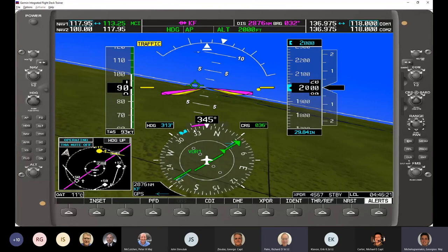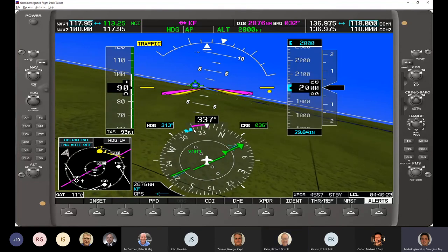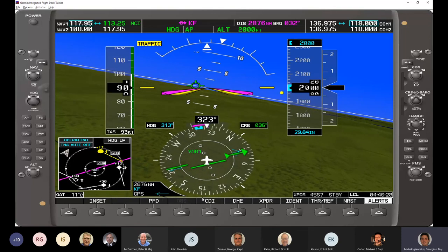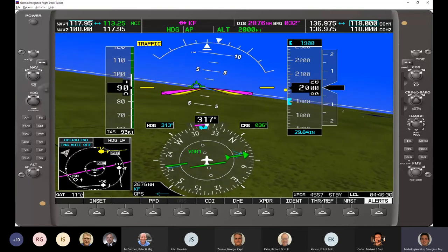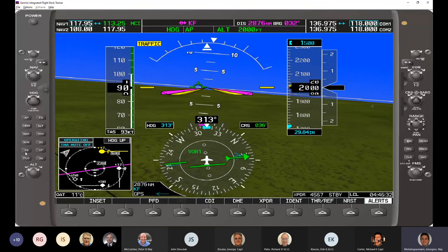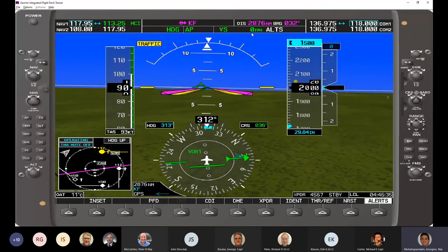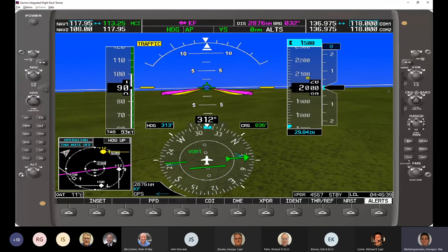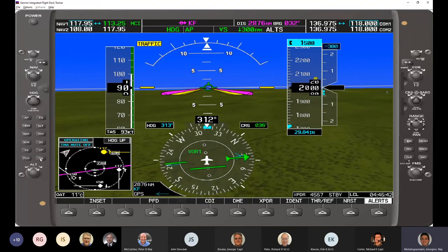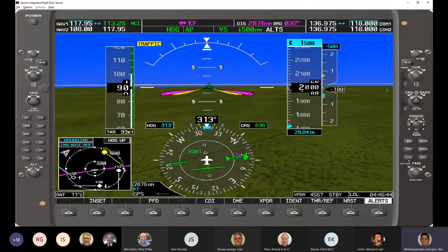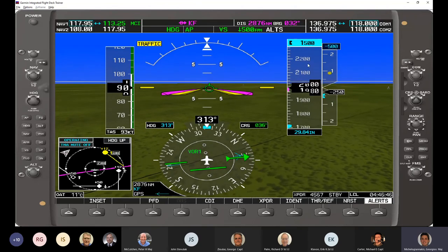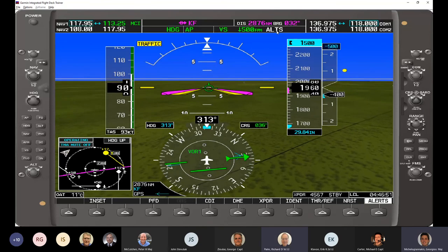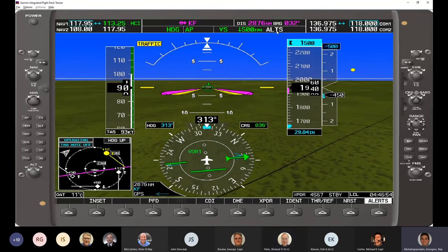Okay, so unfortunately, I don't have a control wheel steering button here, so I cannot demonstrate that. I can show you a descent, but that's almost the same thing. So we basically set the altitude bug, let's say 1500 feet. Going to vertical speed. Notice when I press it, it's at 0. So nothing's going to change right away, assuming I don't change the power. But I can say nose down. Now we're going down by 500 feet, and the same thing is going to happen when the altitude reaches the altitude bug. Altitude select, which is altitude hold, will become active and it will flash green.